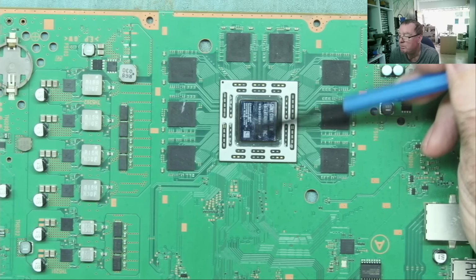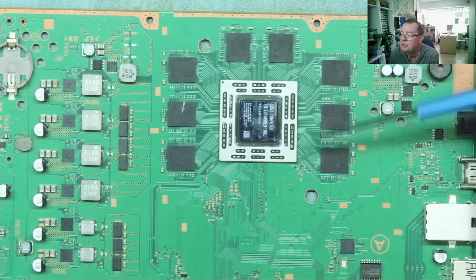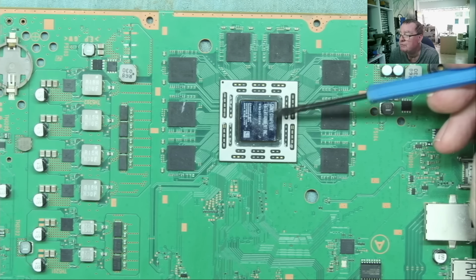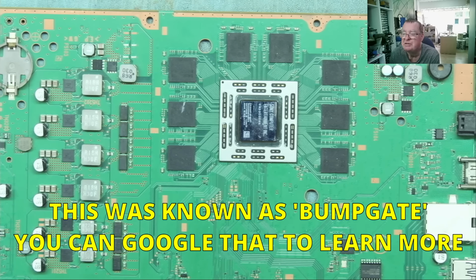Yeah, they're called bumps. And what was happening is, due to defective manufacture, and a number of big companies sued NVIDIA over this, the die was heating up and cooling at a different rate to the substrate, and the bumps would fail. Okay, now this is where this heat it up at work comes in.